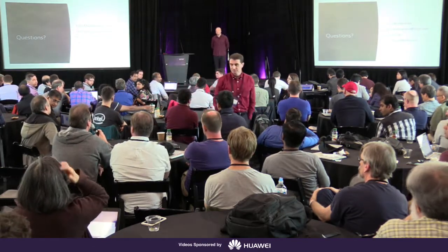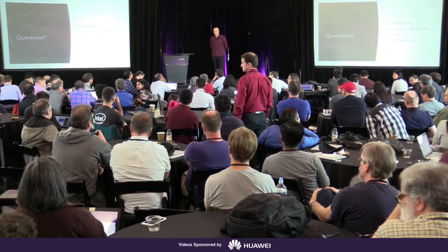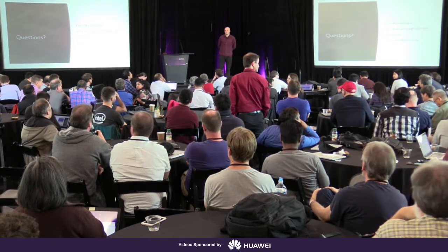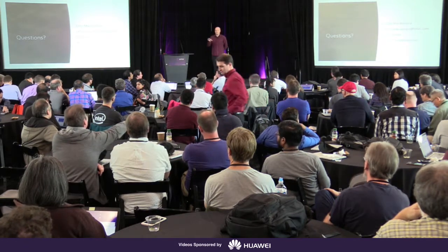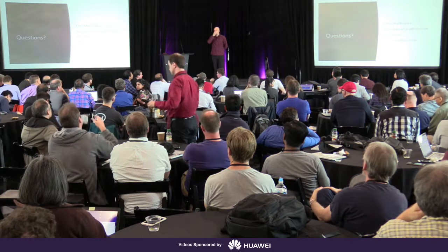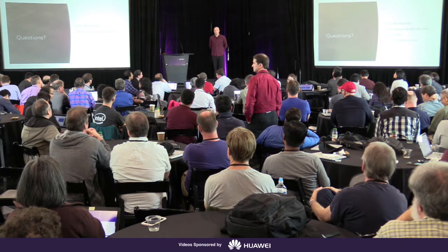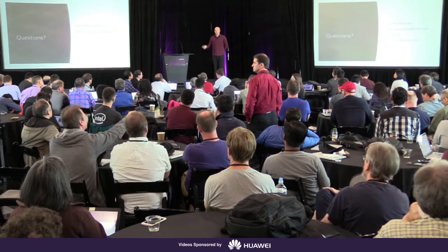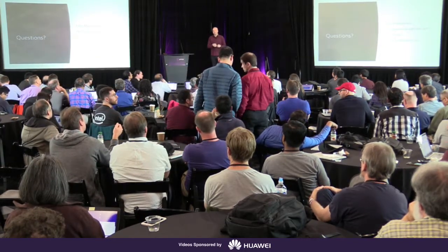What is the reaction time of the power governance here? Because this defines a queue depth somewhere where we have to survive any change in the traffic. The software reaction time is in microseconds, single-digit microseconds. It's literally the time it takes to request that state change. Where it becomes longer is when you have logic tracking packets per second over time. You may want a window, for example, where every millisecond or every 100 microseconds I make that change. So it's cumulative. Does that answer a bit?